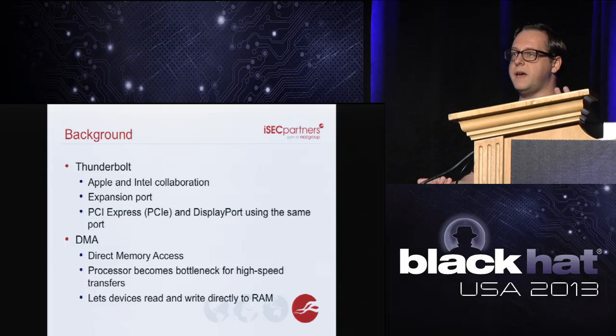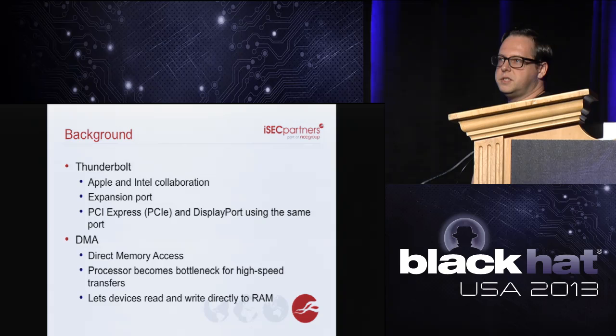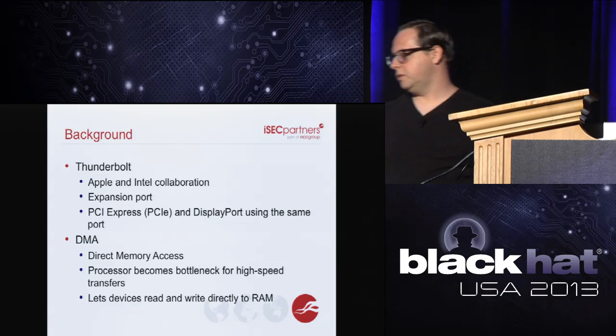As the processor became faster, devices still stayed slow, so the processor would have to wait around for the request to be finished by the device. It was a horrible performance hit. So the engineers decided, let's just have the device contact the memory directly and allow the processor to continue on doing what it needs to do. That was the solution.